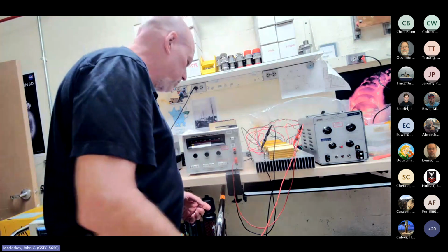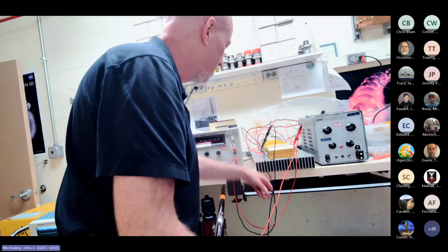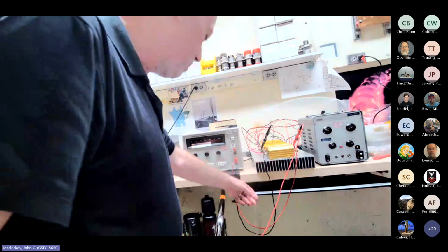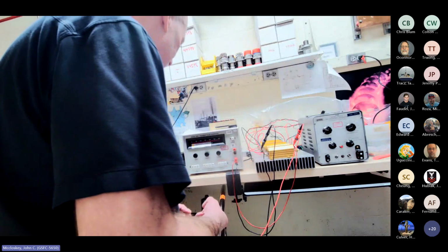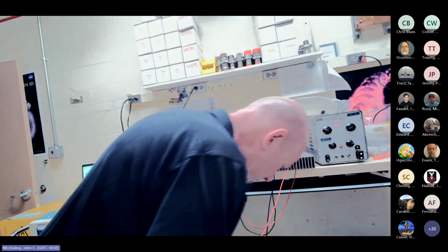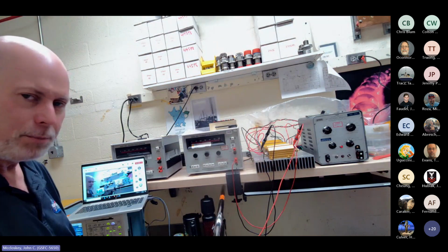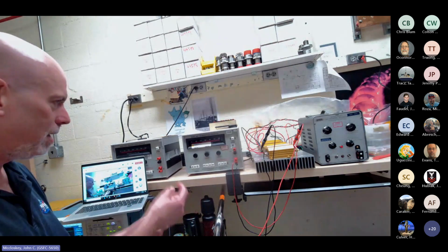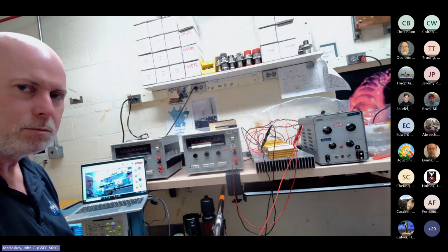Yeah, it's kosher. So we have our pair of banana jacks going across our 5 ohm resistor, and then we're using a differential scope probe. For this, you probably could get by with a single-ended scope probe, but I've gotten very accustomed to using differential scope probes, and that is my preference if one is available. For your pre-calibration step, it probably doesn't matter, but when you're injecting into the EUT, the differential probe really is more important.